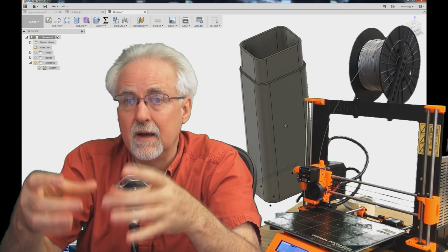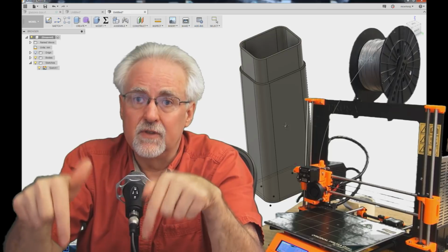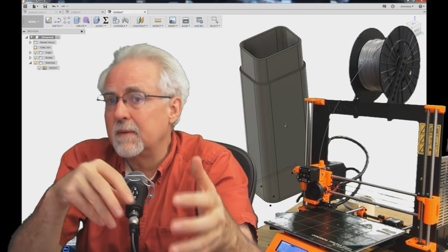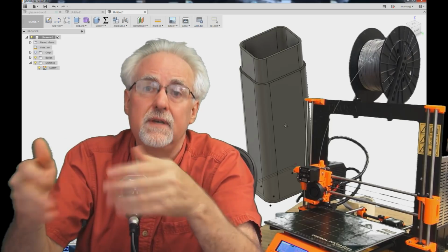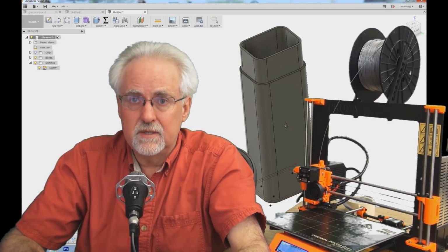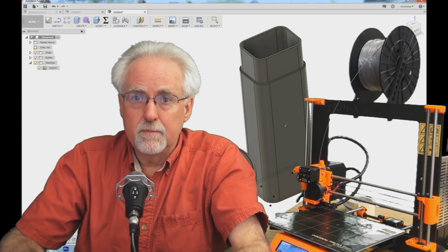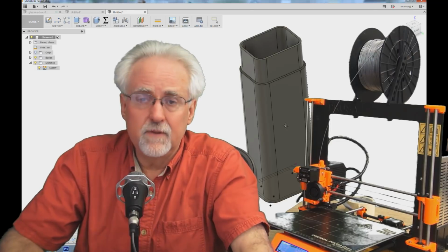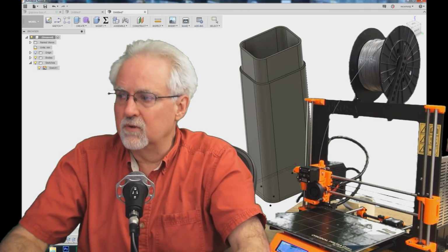The Raspberry Pi always needs to fit in, and the screws always have to be in the right spot, but maybe I would want it thicker, maybe I want this and that. So thinking about the things that you want to build in as constraints, kind of parameter-based constraints that you build in, sort of like our lip thickness is half of the wall thickness. That keeps us out of trouble.